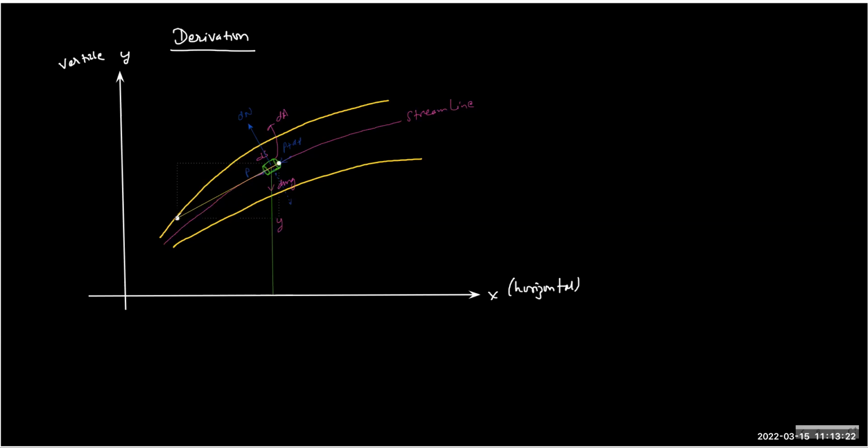Why I'm drawing this tangent, the reason is obvious. I want to know this angle theta so that we can write something mathematically. Now if you look at the perpendicular force to the streamline, this must be 0 because of the equilibrium condition. And this will give you dn equals dmg cos theta, as we know. This is theta.